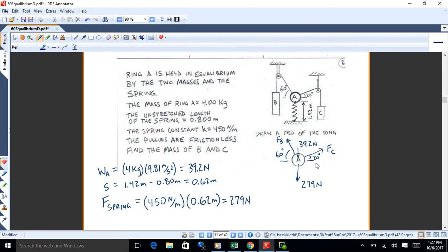Now what we have now is two tools we can use, not much, but we got a couple of them. Remember that when you do forces, you're dealing with vectors, okay? So we treat them like vectors. Sum of F equals 0 is the general equation I've got, but I'll refine that a little bit. I can get two equations out of that because this is a two-dimensional problem. So those are the two equations I can work with, okay? We're going to have to do a bit of trigonometry here, break stuff into components, and add stuff up in given directions, x and y, set them equal to 0, and then we'll be able to solve for the unknowns. Okay?